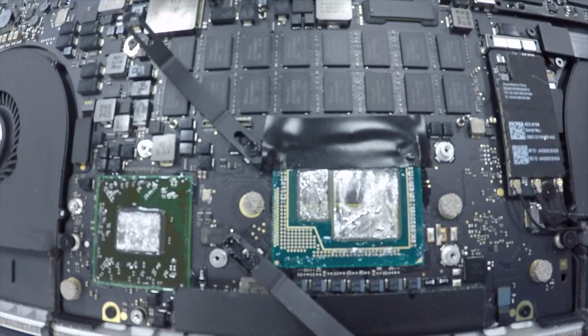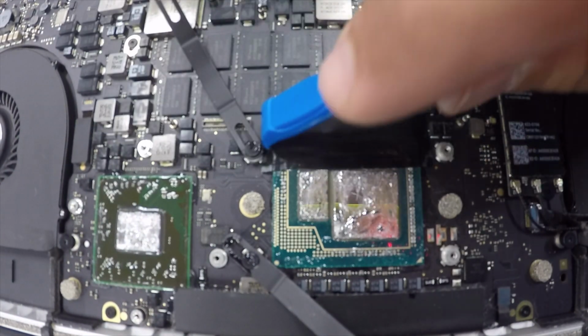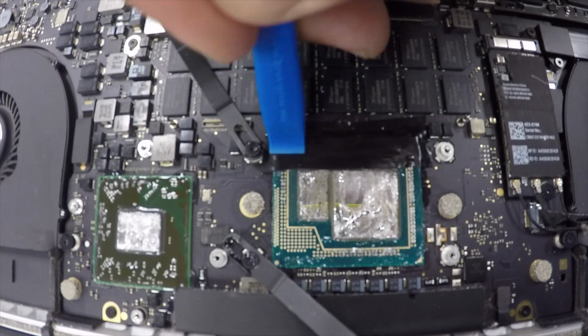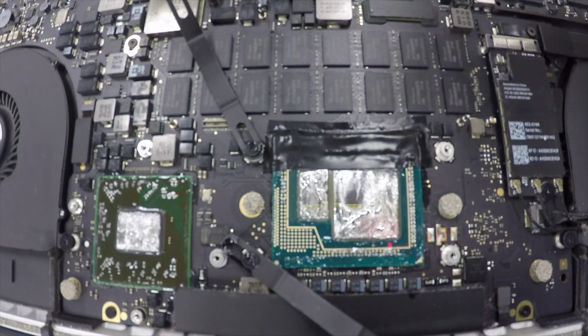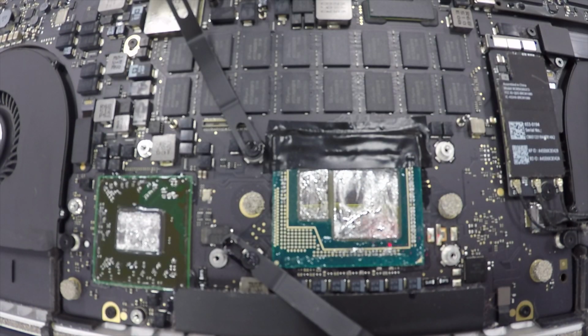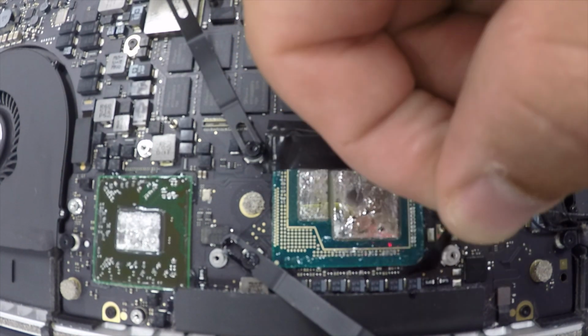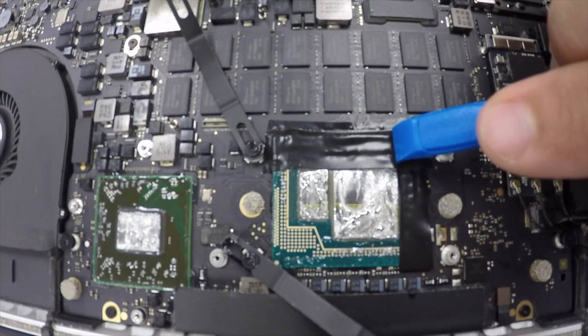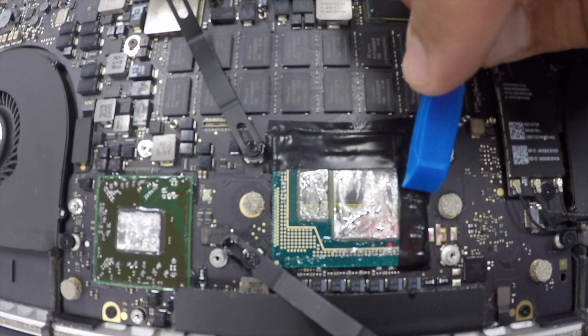So I took the MacBook Pro apart after a few days, and I'm now applying the correct electrical tape to the CPU and GPU board. Now something I noticed that is very concerning is that the CPU doesn't look like it has enough liquid metal, and it has a bare spot. So I'm going to apply some more liquid metal to it and spread around the CPU and GPU chip the correct amount of liquid metal.